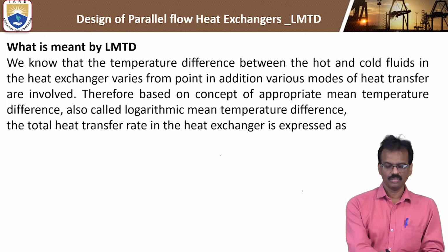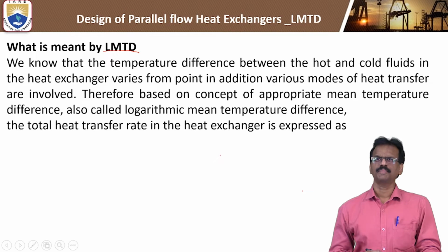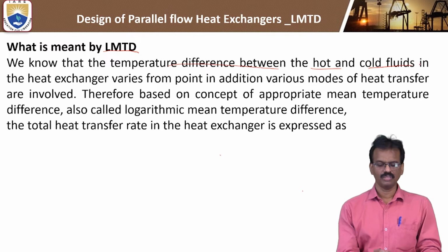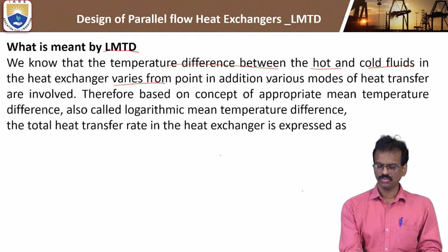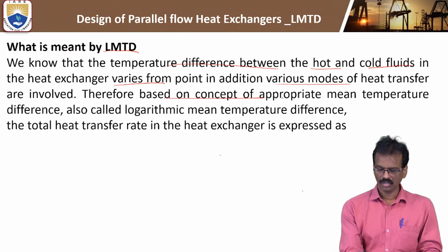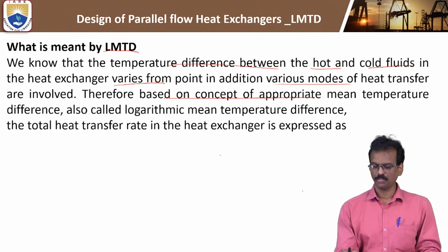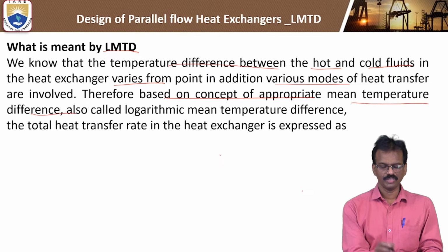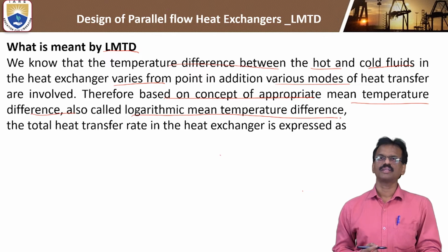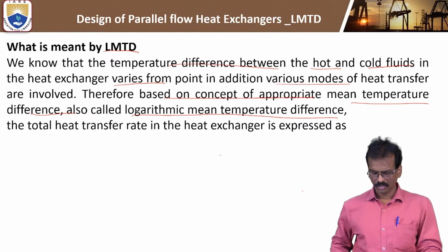So, logarithmic mean temperature difference. You know that the temperature difference between the hot and cold fluid in the heat exchanger varies from point to point. In addition to the various modes of heat transfer, here we will see conduction and convection also. Therefore, based upon the concept of an appropriate mean temperature difference, which we call the logarithmic mean temperature difference, we can calculate the total rate of heat transfer in the heat exchanger.